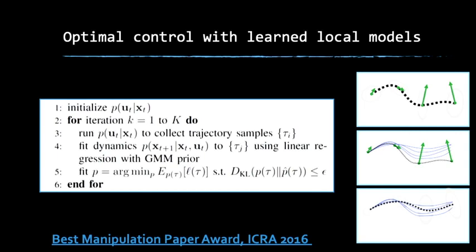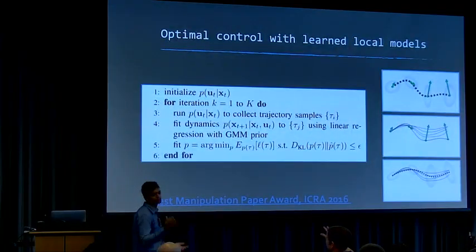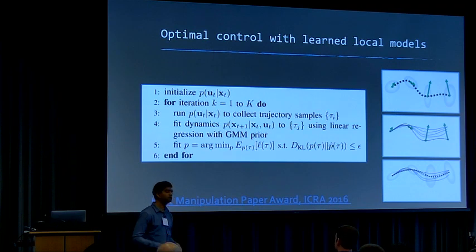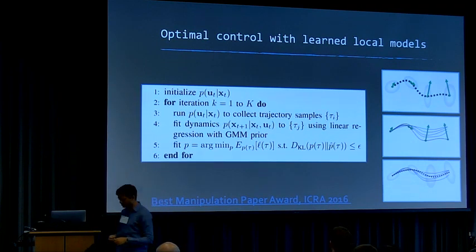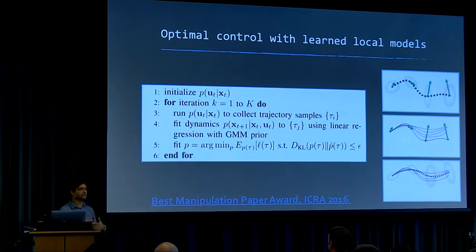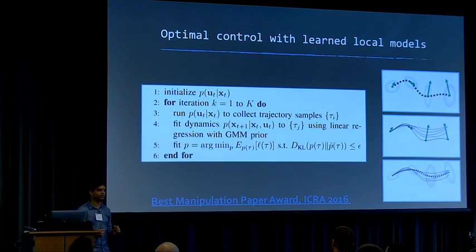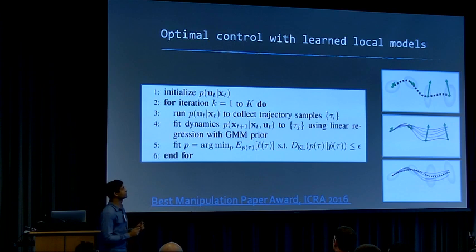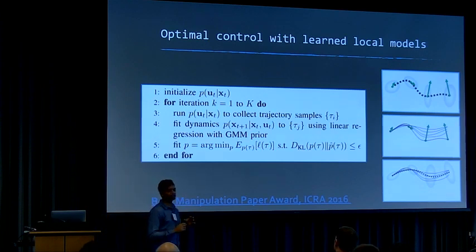So is this basically just like model identification and control? Could you use a neural network model? The details matter, but yes. So we are trying to make a simple model that we can quickly adapt with a small amount of data. And the beautiful thing there is that we are picking the linear model in a way that we can run gradient-based optimization on it to actually get the good effects of MPC on top.